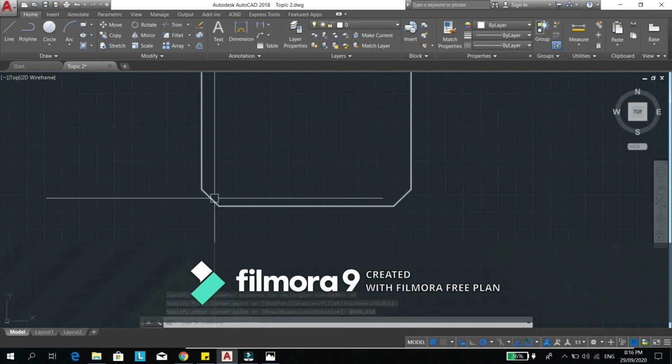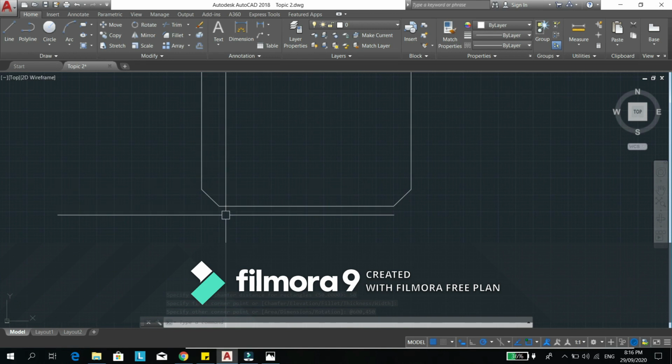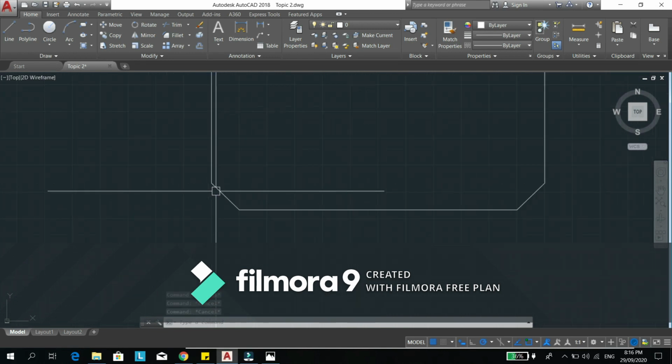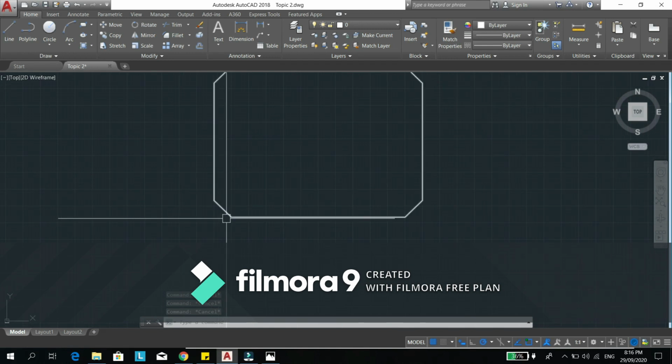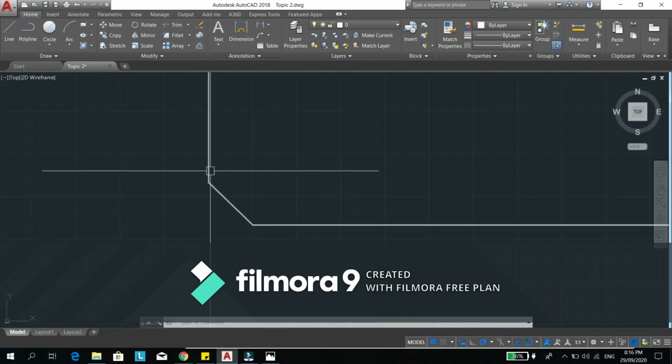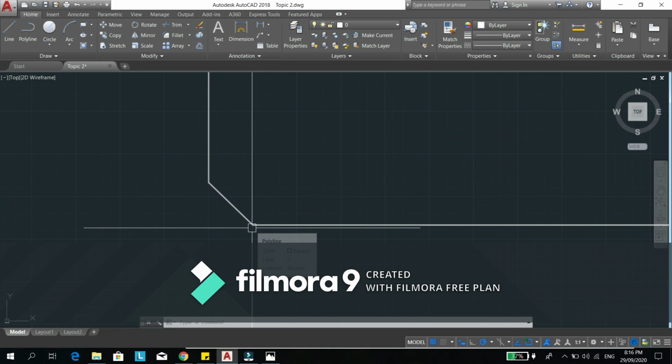So this is the chamfer. Okay. So on the first command, the command you type for C, after that you will be asked the length of the chamfer. So since this, for example, is a square, from the end or corner of your rectangle, 50 millimeters going here, then another one is 50 millimeters going there.